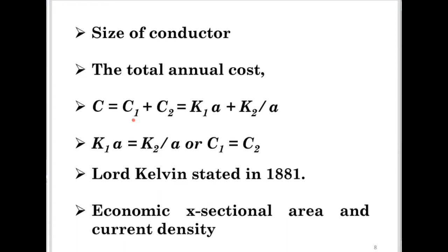Now when we look at this equation, I squared RT, time is constant, it's annual. So it will be a certain number of hours. So how many hours do we have in a year? Yes, that's the correct answer. 8760 hours in a year, 365 times 24.